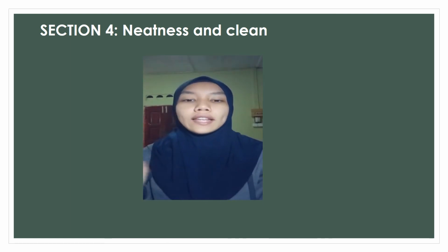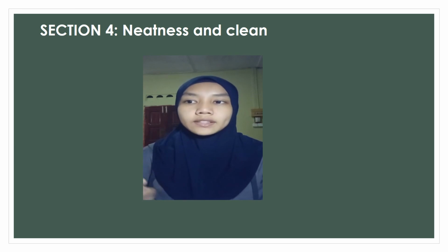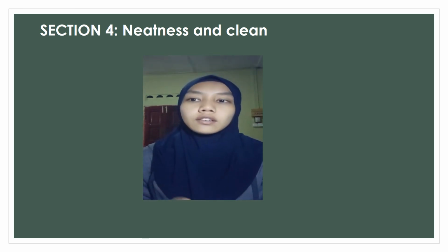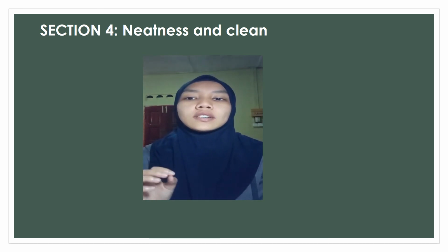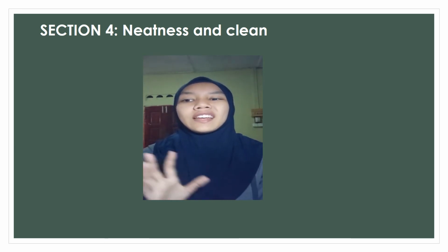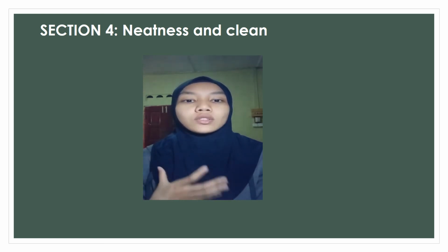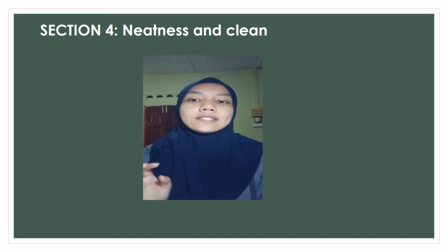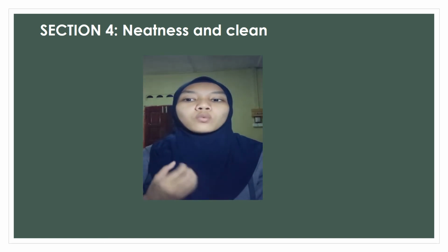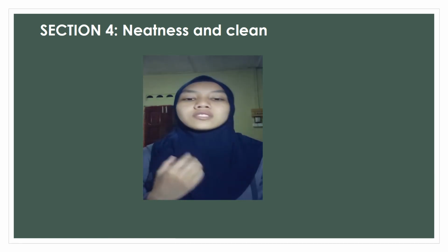When working on a ladder or scaffolding, rest the power tool on a flat surface or in a bin secured to the ladder itself. A falling tool can seriously injure a co-worker or bystander. Never carry heavy power tools up and down the ladder. Step number 6, stop working and turn off power tools if you are distracted by something or someone. Never look away from work when operating a power tool. That's all.